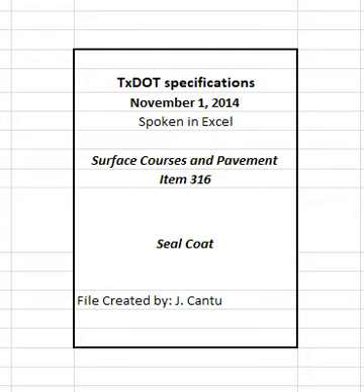2.2 Aggregate. Furnish aggregate meeting Item 302, aggregates for surface treatments, of the type and grade shown on the plans. Unless otherwise shown on the plans, furnish aggregate with a minimum B surface aggregate classification. 2.3 Material selections. Furnish asphalt and aggregate shown on the plans. 3. Equipment. 3.1 Distributor. Furnish a distributor that will apply the asphalt material uniformly at the specified rate or as directed.